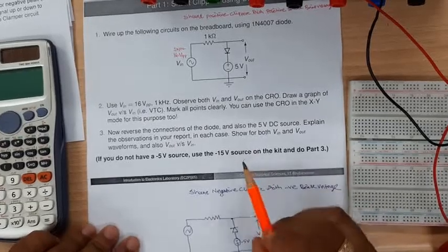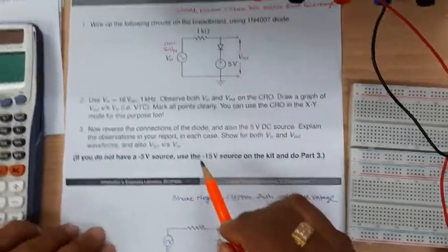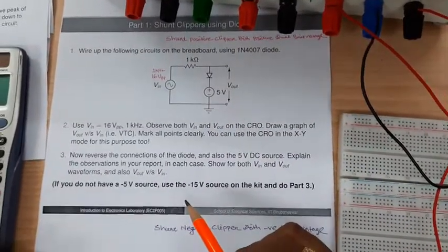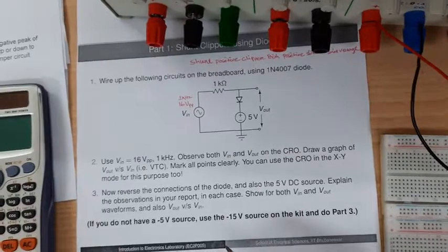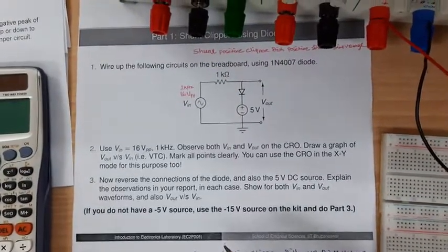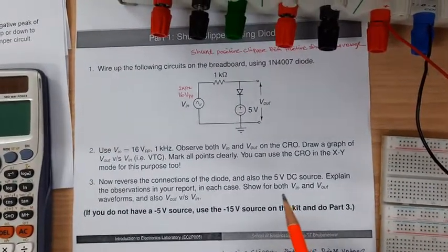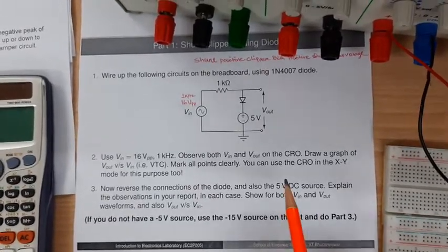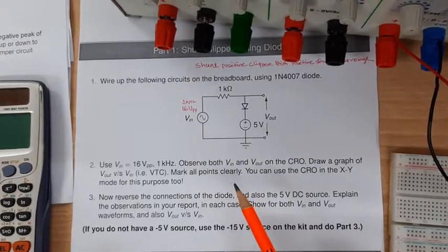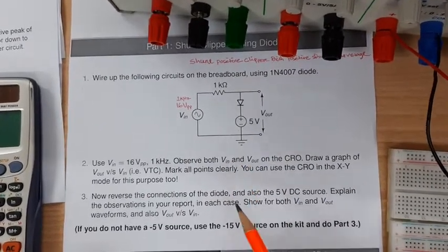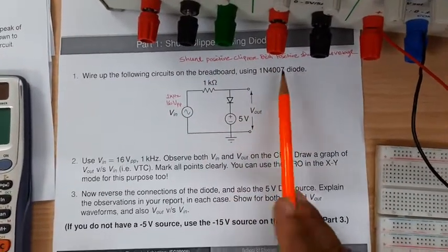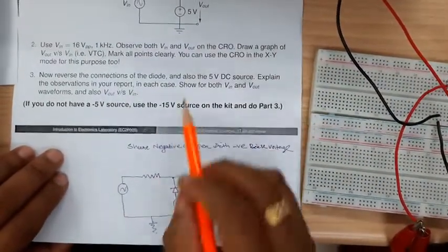We will study about the clipper and clamper circuit. A clipper circuit is an electronic device that is used to remove the output of a circuit from going beyond a preset voltage level, without varying the remaining part of the input waveform. In clipper circuits, we will study two clippers today: the shunt positive clipper with positive shunt bias and the shunt negative clipper with negative bias voltage.